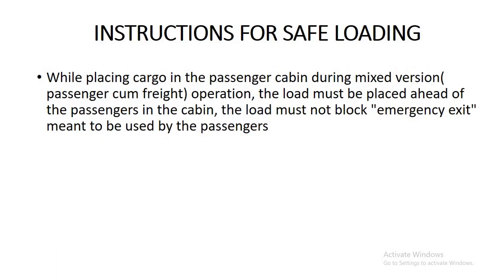Make sure that when you are loading the aircraft with cargo, it is secure. And if you are placing cargo in the passenger cabin during a mixed passenger and cargo flight, then the load must be placed ahead of the passengers in the cabin, and the load must not block the emergency exit under any circumstances.